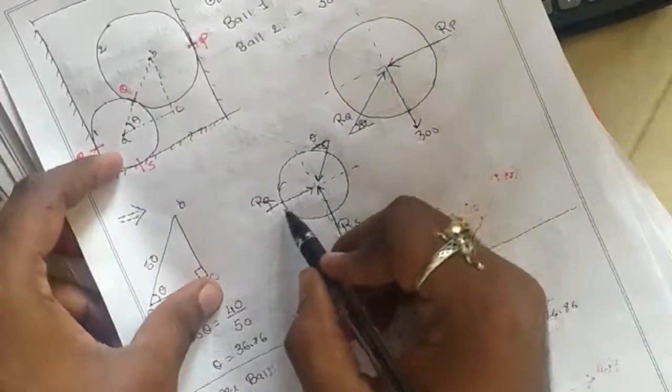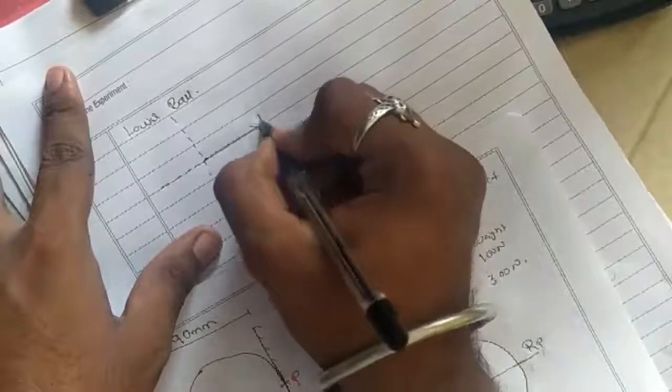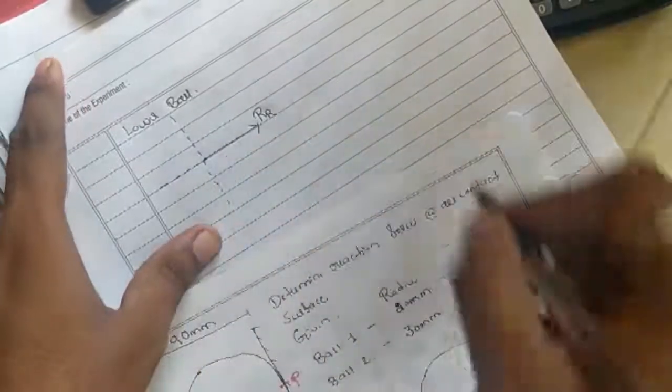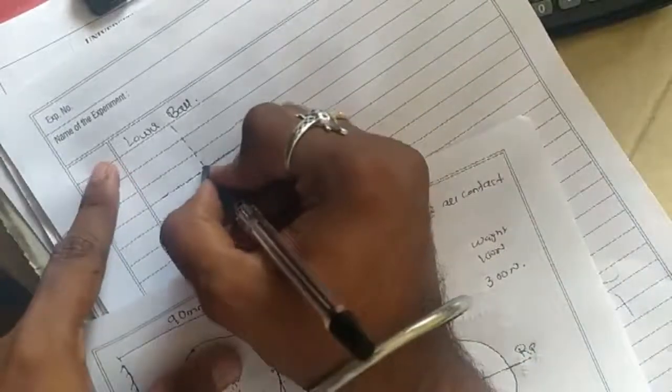Okay, now you can see here RR is drawn passing through the negative x-axis but actually acting in the positive x-axis, so I will redraw it. Then RS is acting vertically upwards, and 100 newtons acting vertically downwards, along the negative y-axis.